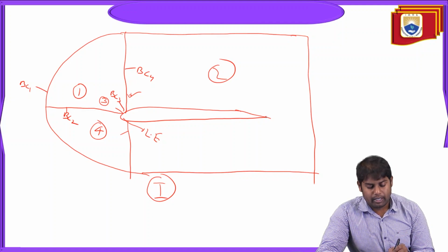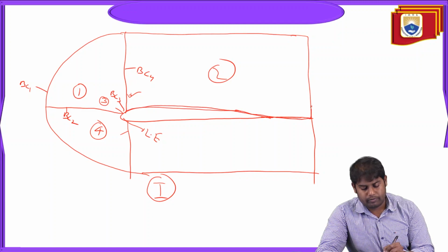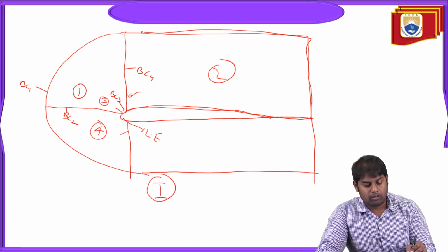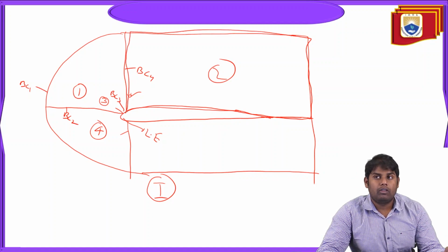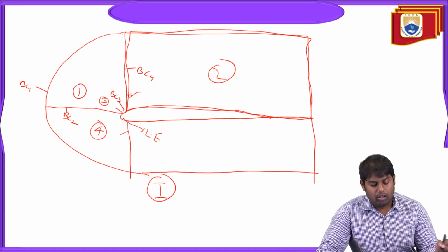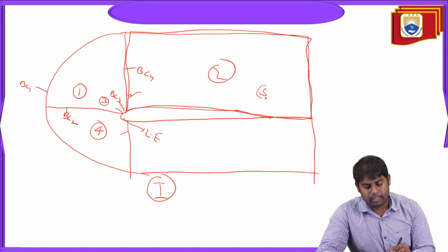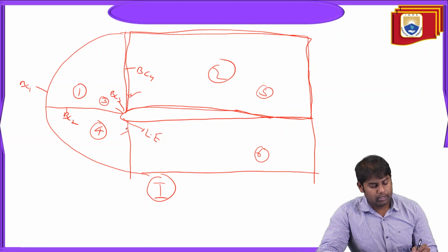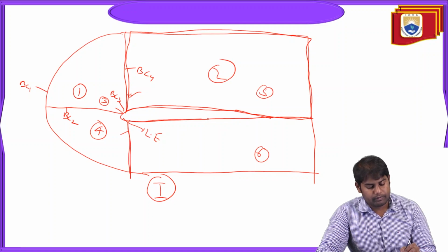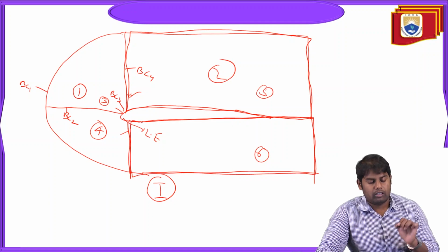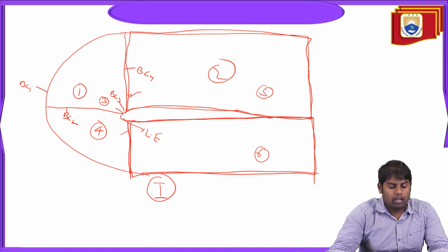That is the default which we have. That's why at the trailing edge of the airfoil we have drawn an additional line. When we draw this additional line, this entity has formed a closed setup. With this closed setup, we can draw a mesh on the top surface. Let us take this as 5 and bottom as 6.